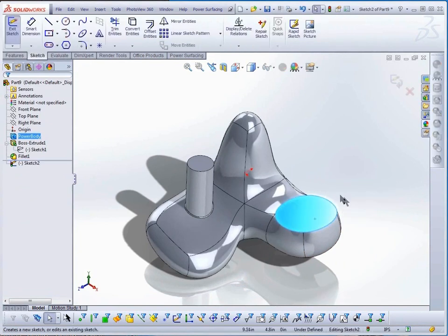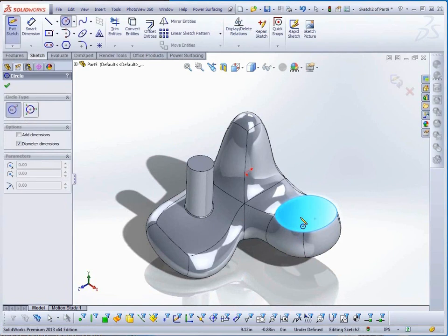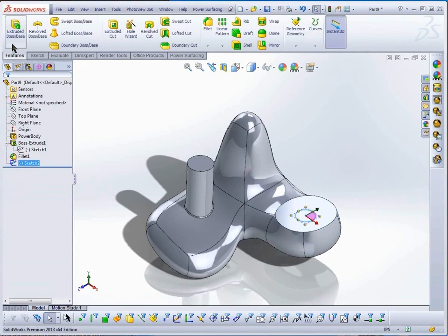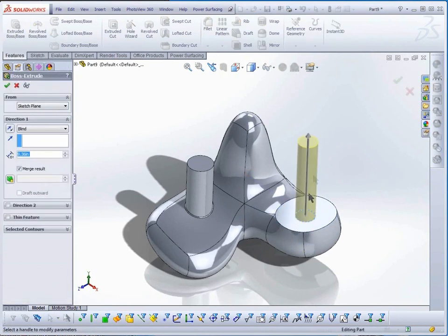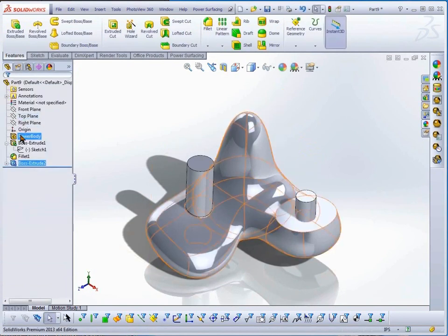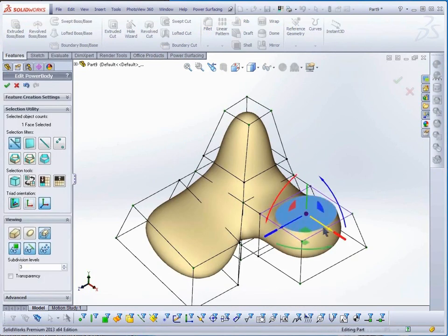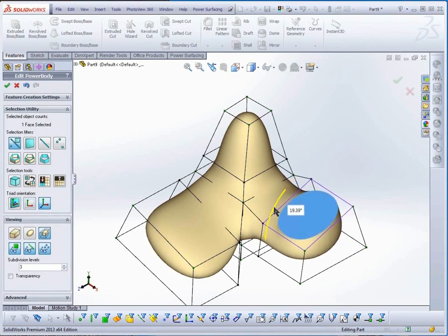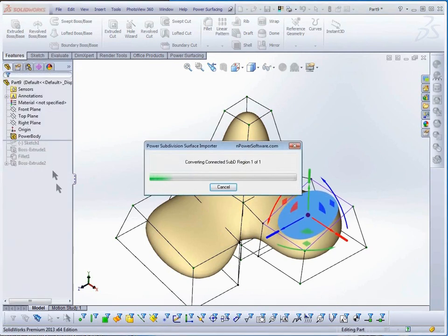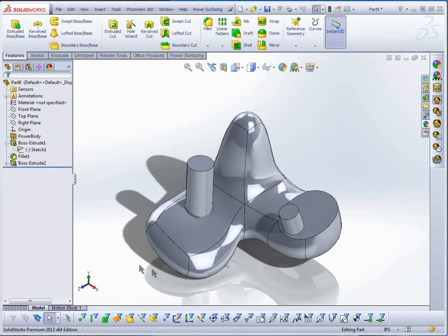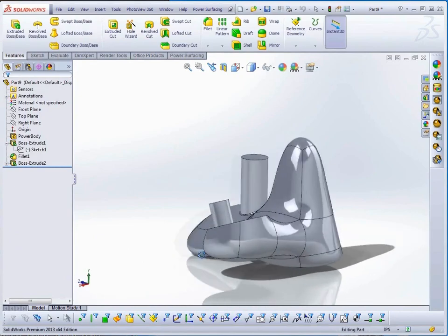Now we can create a new sketch that references the surface. Let's make a circle and use Extruded Boss again. Now go back into edit mode, select the face again, and move it slightly and maybe rotate it a bit. And convert. The circle was not set up for any relationships with the actual geometry this time, but you can see that the construction plane itself reflects the changes.